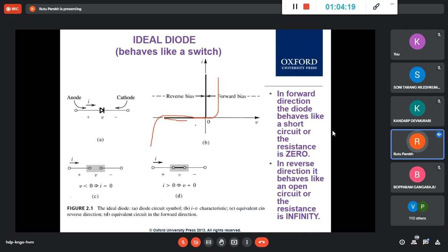Now, when you are using this diode where the voltage is very high, we don't need to be very precise. We can do precise analysis afterwards. For the crude analysis, we use the ideal diode model, where the characteristic is like this. At 0 volt it turns on and is conducting. It is like a wire, a short.